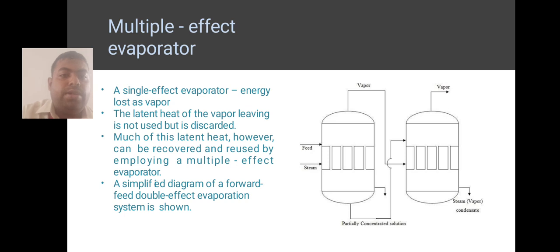Multiple effect evaporator. In a single effect evaporator, energy is lost as vapor. The latent heat of the vapor leaving is not used but is discarded. Much of this latent heat, however, can be recovered and reused by employing a multi-effect evaporator. Here is a simple diagram of a multi-effect.